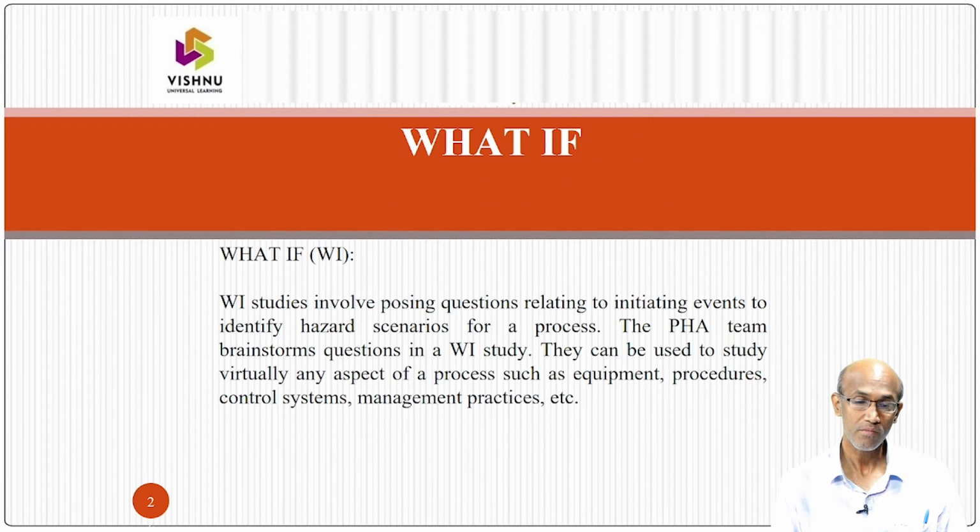What if? WI studies involve posing questions relating to initiating events to identify hazard scenarios for a process. The PHA team brainstorms questions in a WI study. They can be used to study virtually any aspect of a process such as equipment, procedures, control systems, management practices, etc.